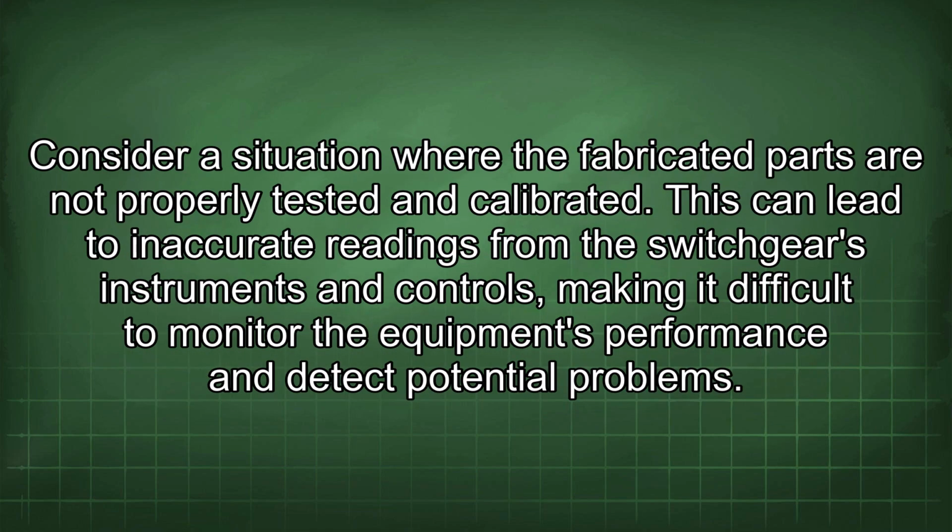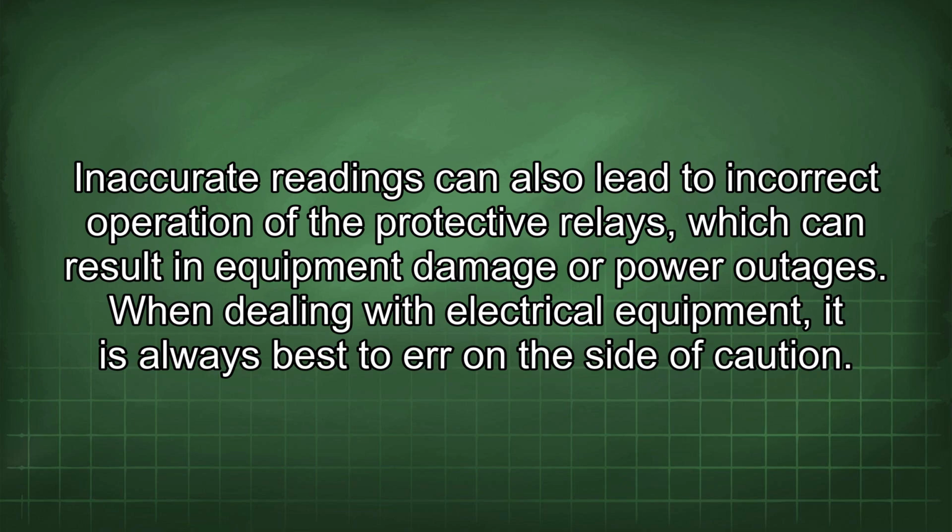Consider a situation where the fabricated parts are not properly tested and calibrated. This can lead to inaccurate readings from the switchgear's instruments and controls, making it difficult to monitor the equipment's performance and detect potential problems. Inaccurate readings can also lead to incorrect operation of the protective relays, which can result in equipment damage or power outages.